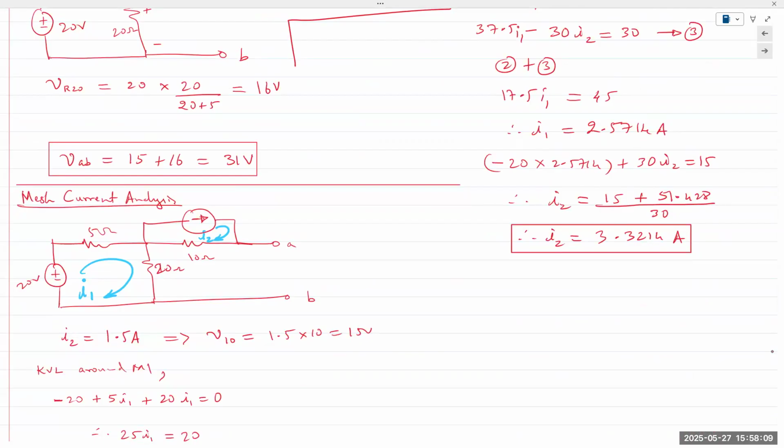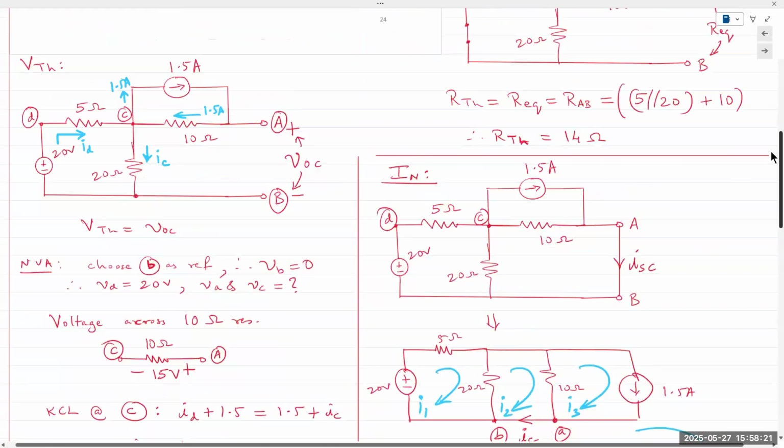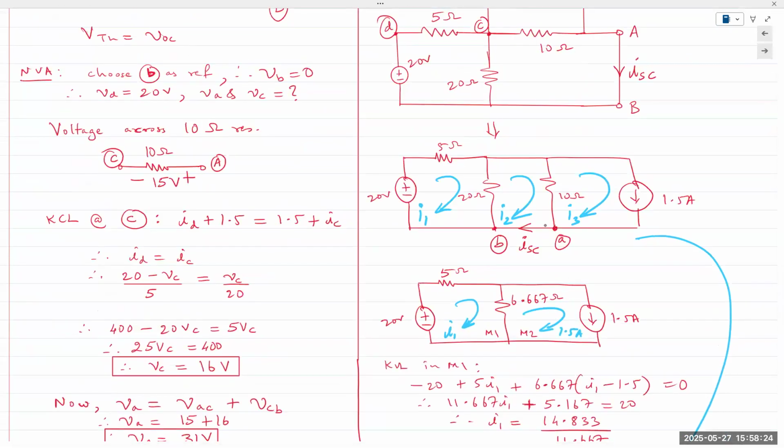Did anybody solve the equations directly? Is mesh current analysis. So there might be an error somewhere. I2 is the mesh current, and I2 is flowing in this part right there, ISC. So the value that we find for I2 should be ISC, because it's flowing in that mesh. 2.21, direct solving. Okay. Sure, yeah. 2.21 times 14 gives me 30.94. 2.21 is correct.